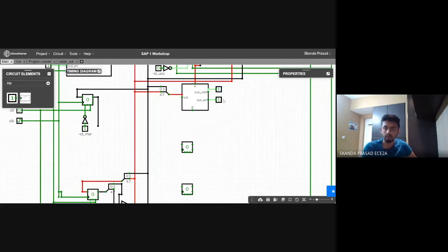Now, after the accumulator, we need to build only 2 more registers, that is the B register and the output register. Now let's build the B register. Consider this to be the B register. Its output has to go to this, as you very well know. I'll just take this property. It continuously drives the adder subtractor. So output is done, and I'll just take care of the clock.